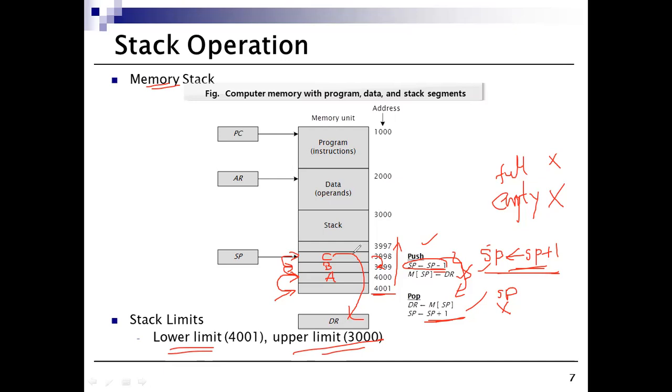The second operation is updating the stack pointer. Okay, in that case, it is always pointing to an empty location. Accordingly, the pop operation will be done in reverse. Okay, so likewise, if you mix the things, you can have 4 ways of organizing your stack.